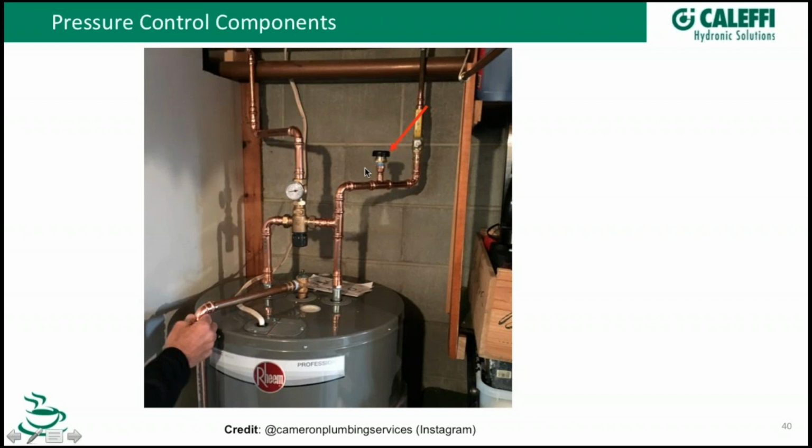Now, some codes require this additional valve, and again, that'll have to be an ASSE listed valve for the application. It just allows air to come in, so you can't suck a negative pressure, a vacuum, on that tank and have it collapse inward, which is actually what it does. The other thing that can happen to a gas-fired water heater, if you don't have a valve like that and you get that negative condition, is it can actually squeeze the flue pipe in the center closed.